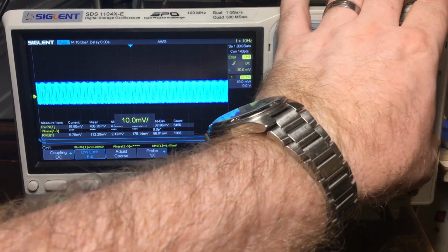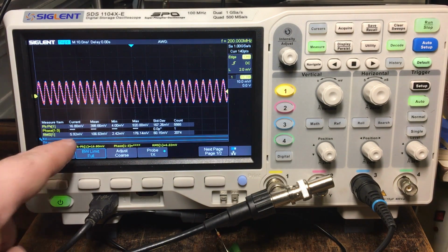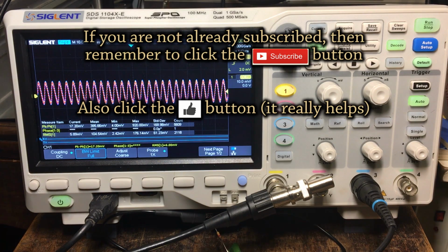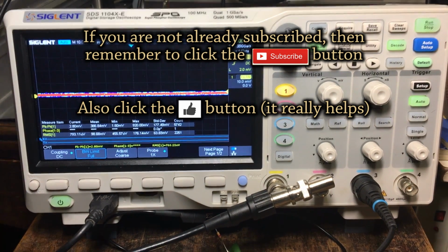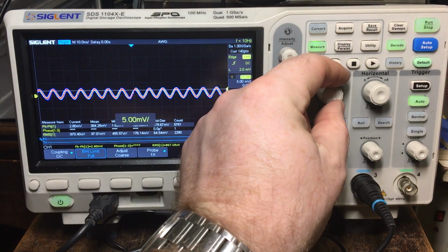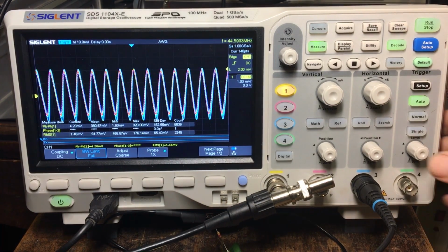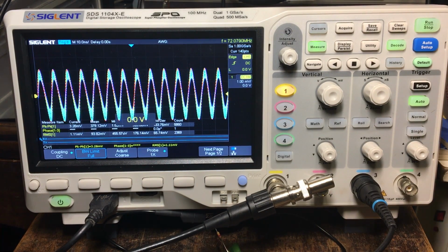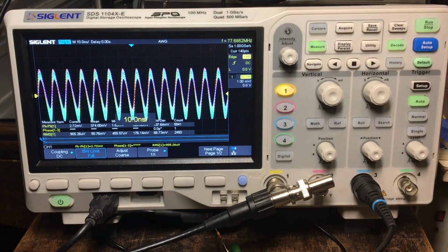That's in the noise. Oh, trigger's in the wrong place. It's not hopping. And there we go. 200 megahertz. But you can see the levels have dropped right off there, so obviously it's not meant for 200 megahertz usage, really. That's 300 megahertz, and you can see it's right down in the noise. Okay, but it's still there. You could still use it. Counter can't read it though. No, it's out of the range of the hardware counter.